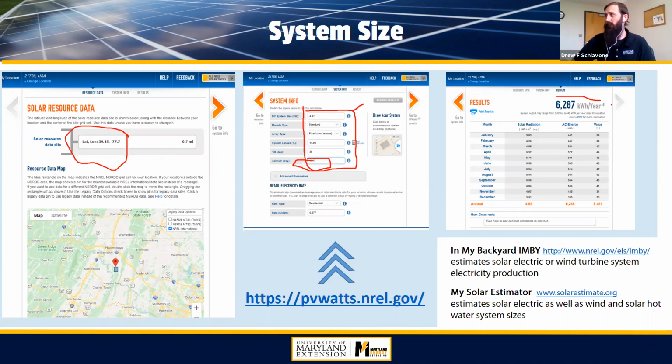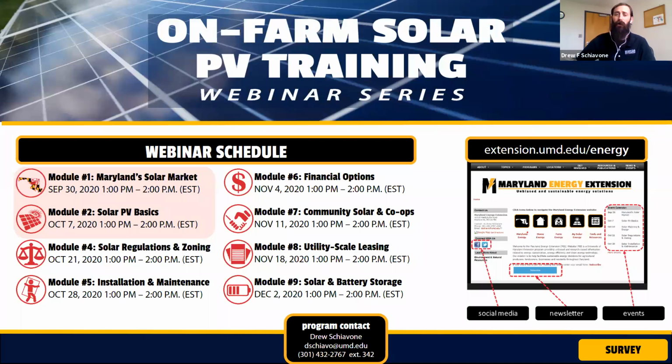In this case, we don't get exactly what we did on paper. What we got here is 6,200 kilowatt hours per year. So this is a more robust way of looking at it. I encourage you to use that website, and I've included some additional resources here, and we'll touch on these in subsequent programs as well, in my backyard and my solar estimator, some other useful tools. But again, explore that PV Watts, and you'll find some useful applications for that.